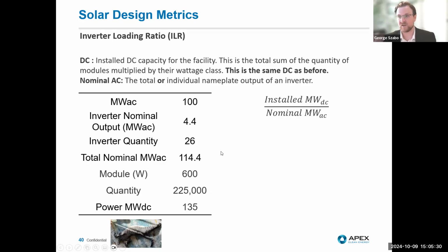For those that have a deep background in electrical design, you'll know what that means, but we'll talk about that later. Basically, the solar facility needs to be capable of taking voltage off of the grid, but also being able to put more voltage on the grid, which helps with voltage regulation. Part of that is the reactive power that can be output by inverters.